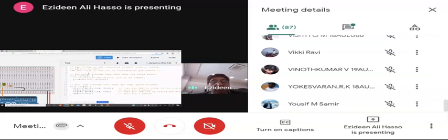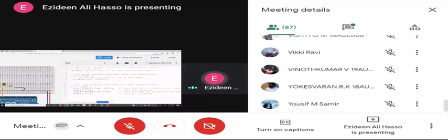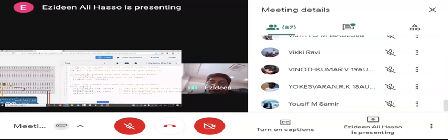Anyway, before the setup is the variable declaration. So I'm declaring a variable called LED, whose value is 13, and it is an integer. There's no decimal point here, like 13.5, because it's a pin number, pin number 13, so I don't need any decimal point. This is why I defined it as an integer. Int is short for integer.